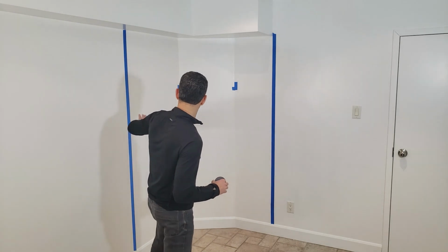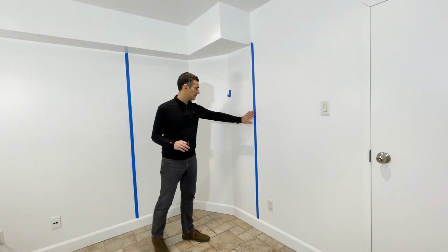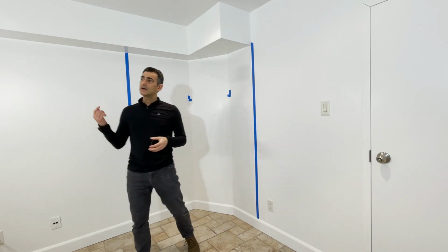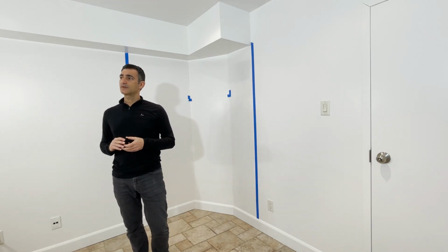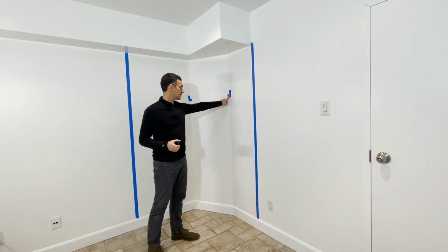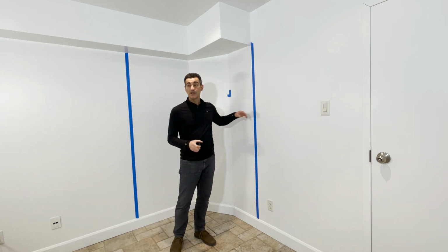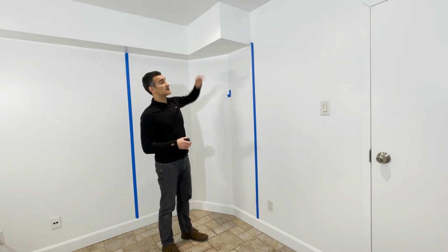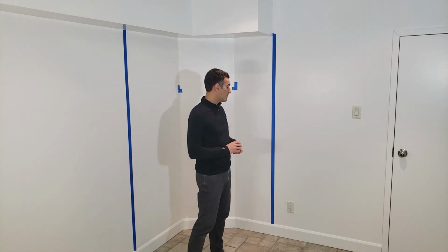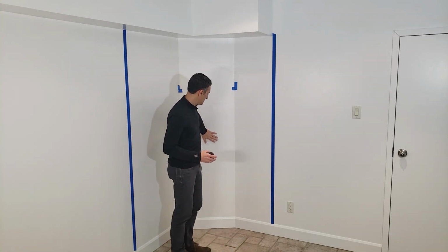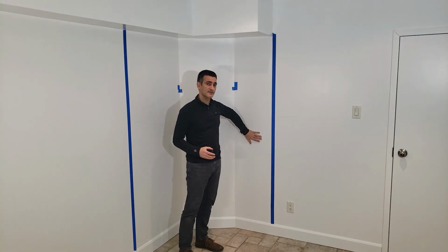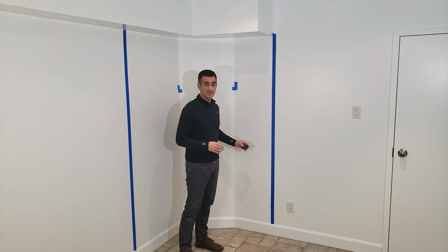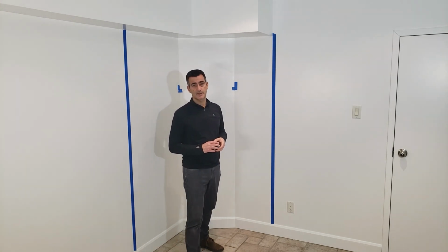So I've actually put up some tape here on this side, and then I have a couple in between here. I'll explain why I have those up there in a minute, but these parts where there's high contrast, you're going to find that they will reconstruct pretty well. You might even get the corners reconstructing okay. But you're going to get these areas that are just open and there's nothing there. These are freshly painted walls, so unfortunately, the reconstruction is just not going to work out all that great.